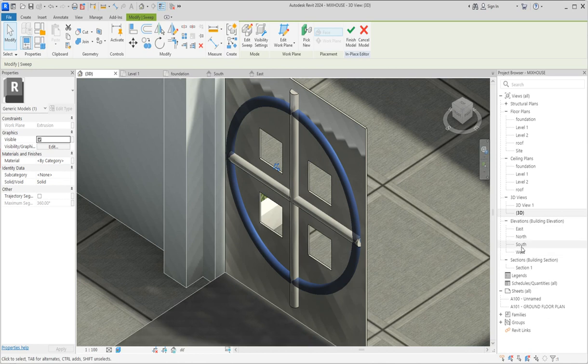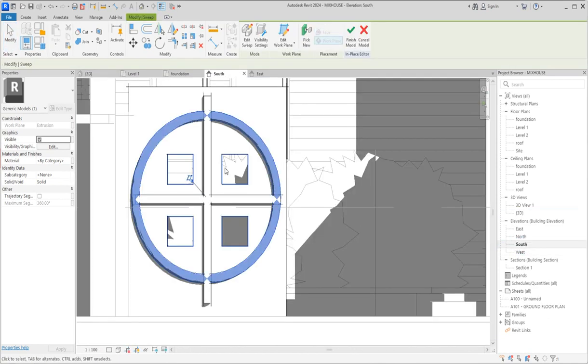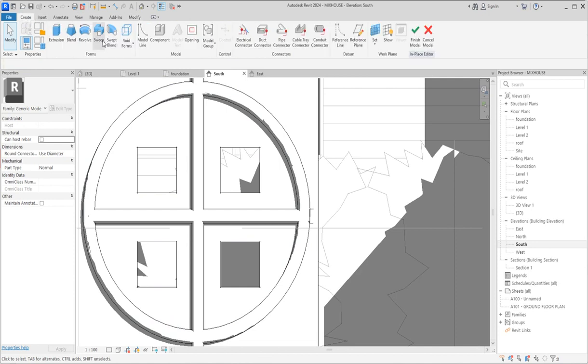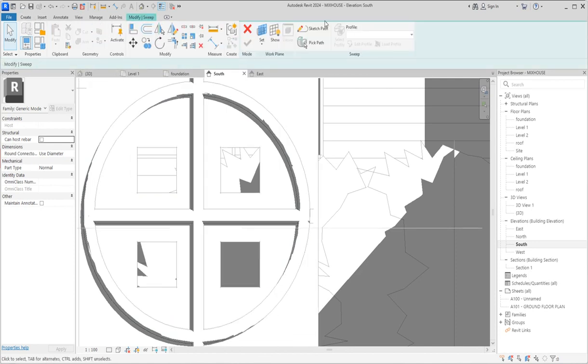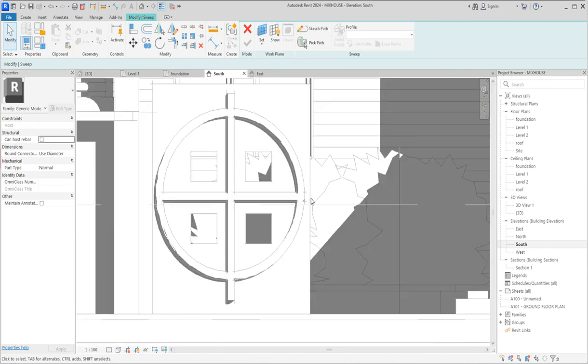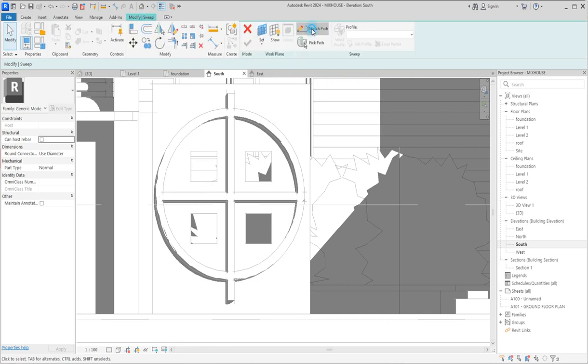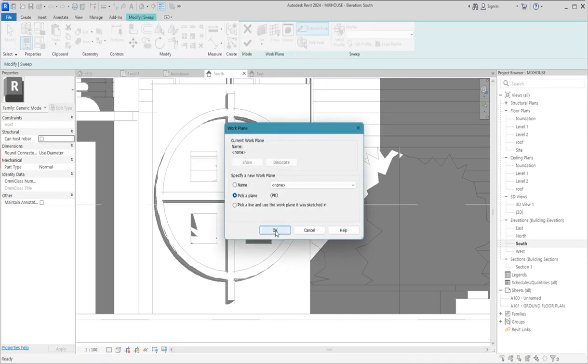Now what we need to do is go to start elevation. So here we need to design something special again. Create this one and use the same sweep to do whatsoever you want to do. So click here. If you ask me how I do the void, it's just that when you are in this sketch mode, you are not going to leave. You just go to create, and at the same time click on void, and everything will come back for you. So creating sweep, then just click on the